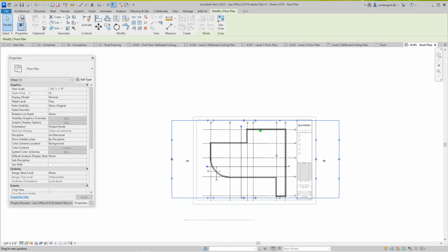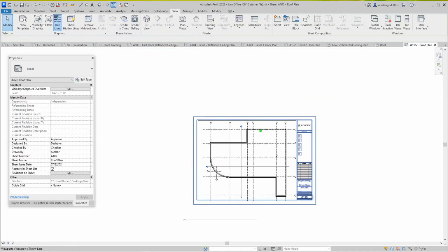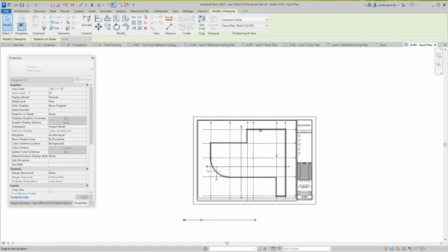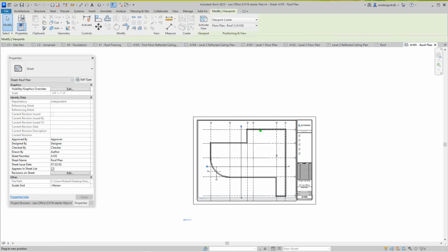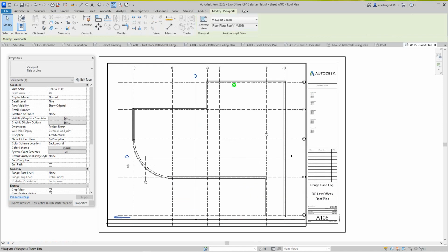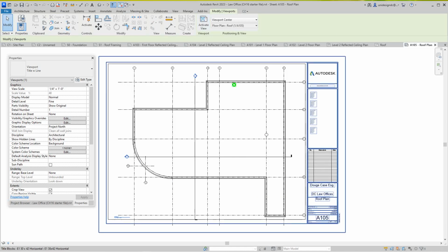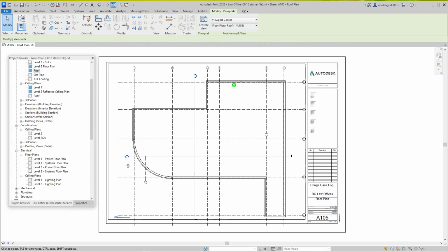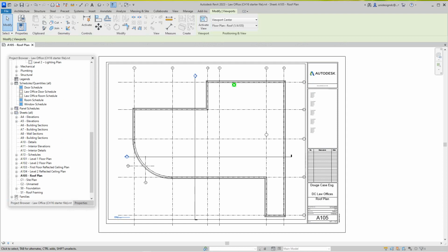Now we have to go through every drawing discipline, electrical, mechanical, so I think the next discipline would probably be structural. We'll do this up here like so. So that's basically how you do the plan. So we've got our plan drawings all set up. Go to my project browser here, and there are our drawings in there. So we've got our level 1, our level 2, and our first floor reflected, our second level, and our roof plan.